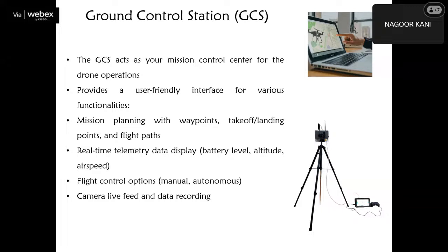So it has an antenna that transmits everything. Every command we are providing, not only that, it will act as the transmitter and receiver. The data captured by the drone's sensors will be transferred through this antenna to the tab of the GCS or mobile. It acts as a control system as well as a data transfer system. So that is using a 2.5 gigahertz frequency transfer.